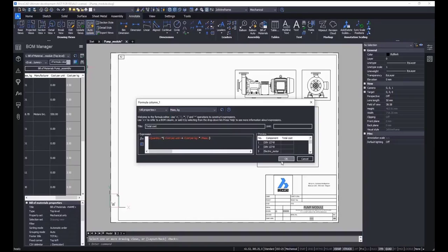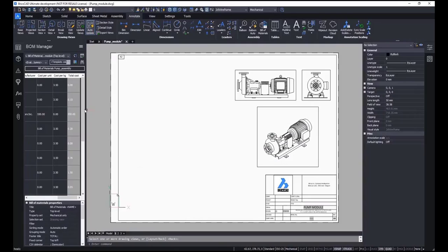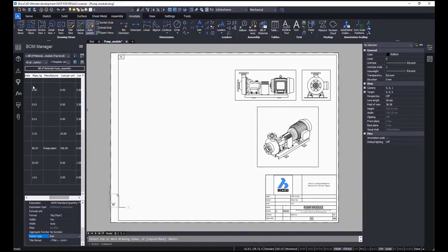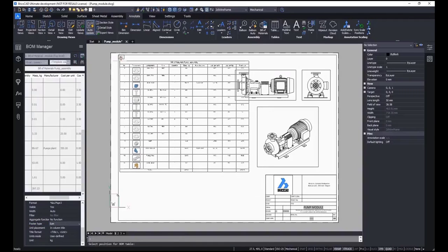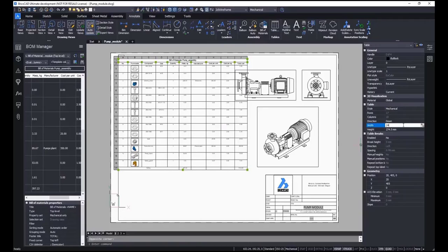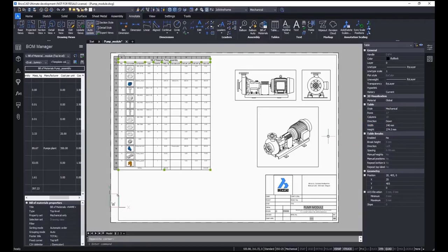As we know the cost of every component, we can now easily compute the total cost of our assembly using the footer row that automatically sums up the cost of all components. But why do we do that in BricsCAD and not use spreadsheet software? Because our goal is to put the BOM table on the layout sheet, which will be automatically updated when we change the structure of our assembly, geometry of each part, or their native or custom properties.